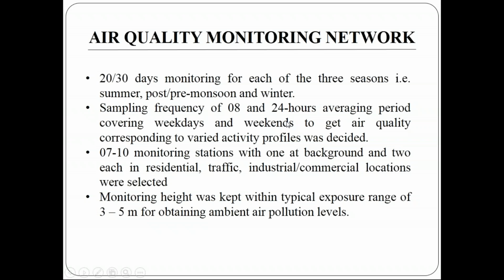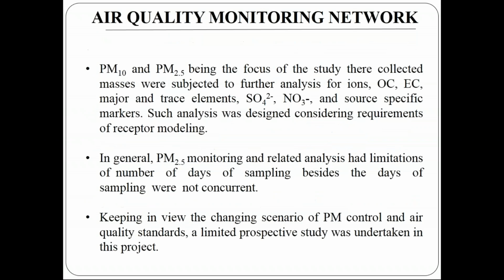So for this air quality monitoring network, we need to go for monitoring as per your standard chart, 3 months or 1 season, or sometimes we need for 30 days. And sampling frequency will be 8 hours or 24 hours. It is depending on your TOR or specific research activity. And also the monitoring height should be more than 3 to 5 meters above the ground. There should be no obstruction or barrier where we need to install our FDS, RDS.